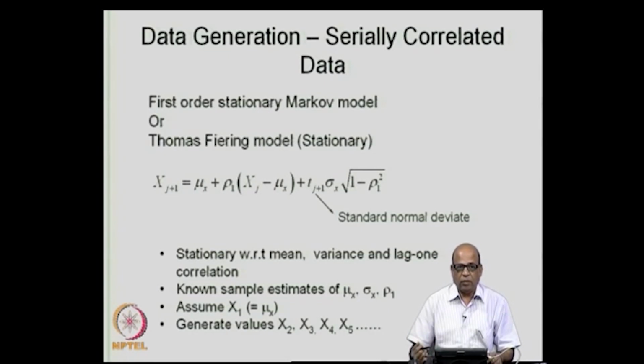If there are certain cases where the model does not perform well, either in terms of the standard deviation or in terms of lag 1 correlation, it then means that the assumptions that we have made in building this model, namely that it is a stationary model and that the flows follow a normal distribution, may not be valid for the data that you are using. So, a test for the model to be valid is that all the three, namely the mean, the standard deviation and the lag 1 correlations must compare well between the historical data and the generated data.